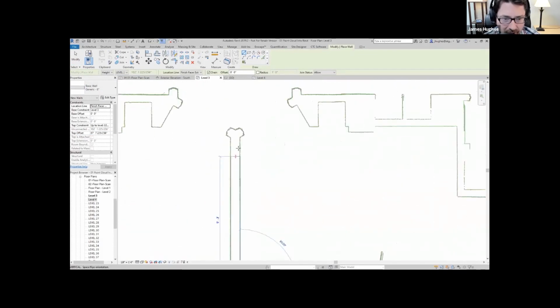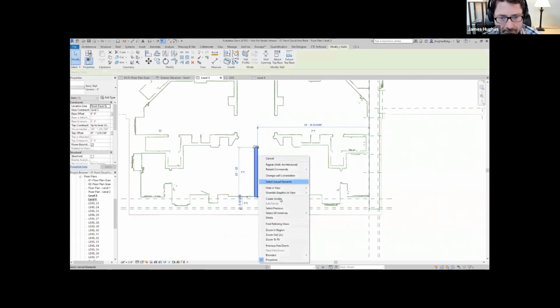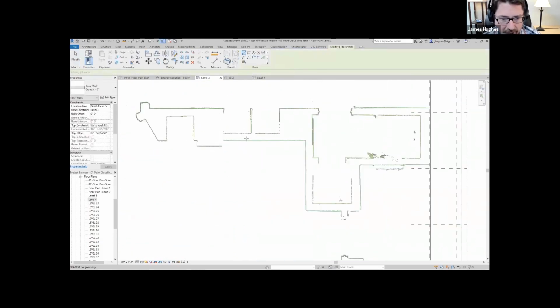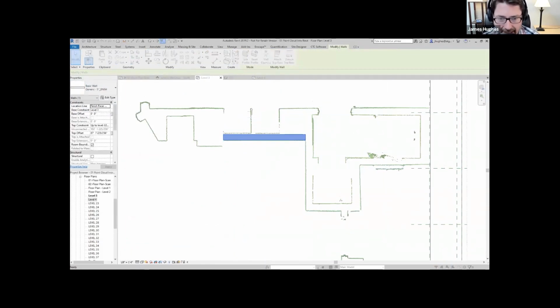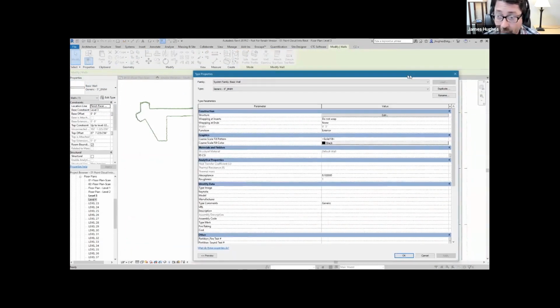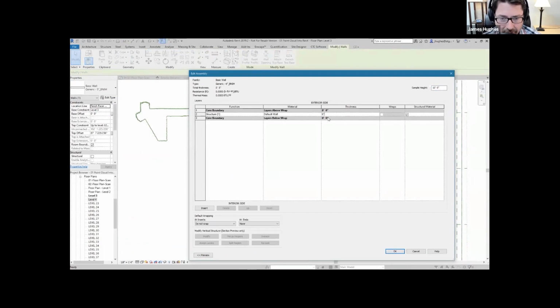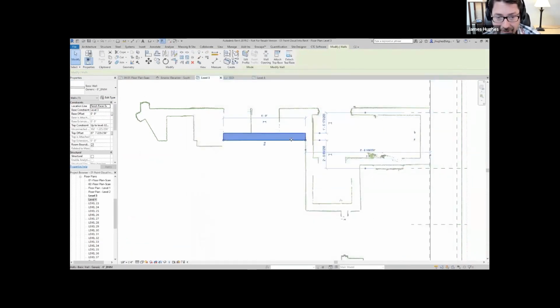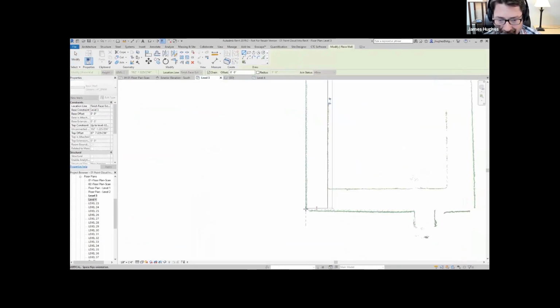Later on, the customer is going to change those out to known construction. And you can just right click, create similar. Notice that you're getting snaps along point clouds. That's pretty new. I think in the past 2 years, Revit has started to create alignments along the axes of point clouds. It recognizes that cluster of dots as a surface or a potential surface and acts as an axis for you to align to automatically, which makes this, even if you slowed it to half speed, still a pretty quick process to lay out.